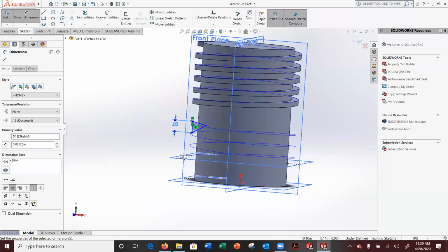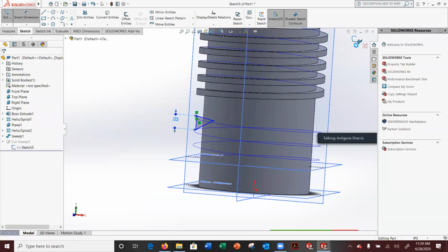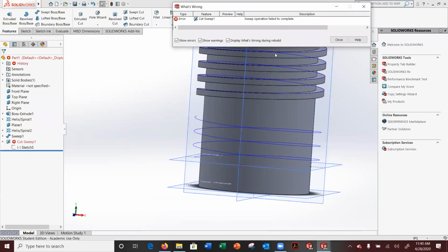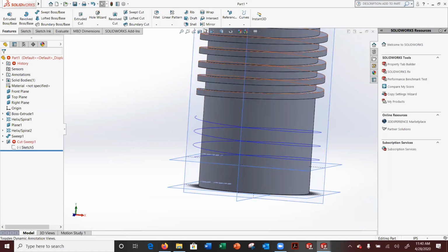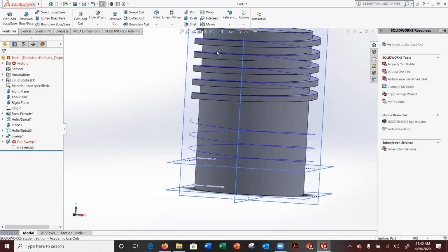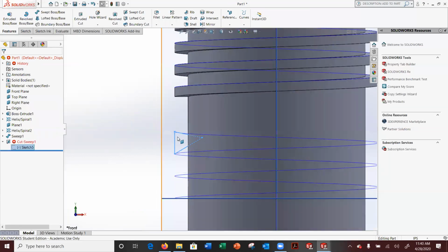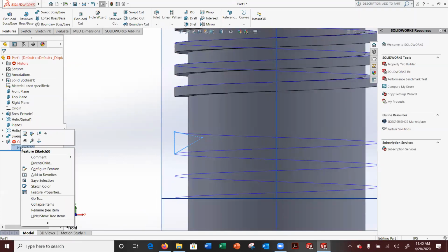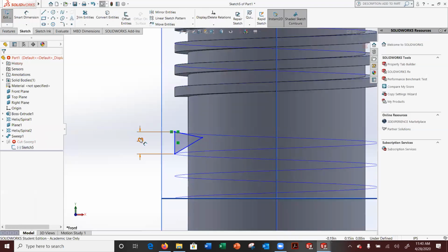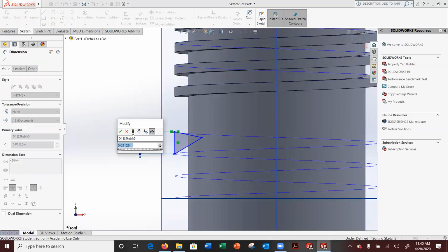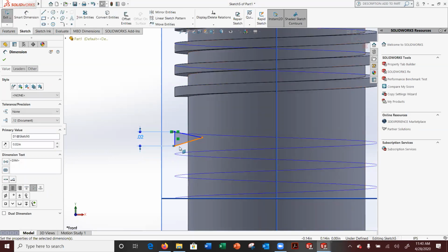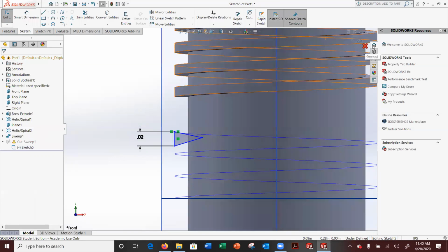Now that should be interesting because that should cause potentially some issues. There we go. If your sketch overlaps itself, that's what I was trying to show. See how the sketch overlaps to the next sketch? Then it will fail because that is the pitch. So your shape has to fit within the pitch. So if I made it 0.02, slightly smaller, maybe not enough, let's go ahead and see what happens.